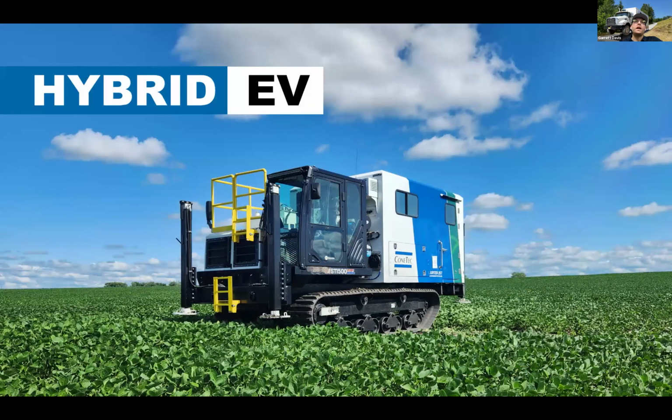We've even got now hybrid EV machines. You use the diesel Tier 4 engine to drive the machine to your site. You turn off the engine and then you work on battery power, pushing your CPT, running your dissipations, pulling your tooling. And then when you want to move on to your next site, you turn the engine back on, which charges your battery as you're driving, and you keep on pushing.